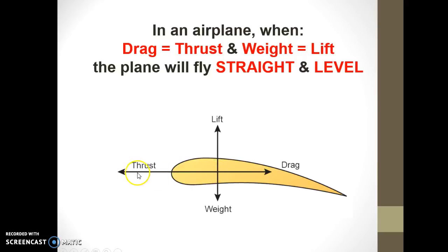We've got the thrust, which is our forward motion, which in your cars will be created by the CO2 cartridges. The drag, which we talked about, is either from that frontal pressure or the rear suction. Then we've got lift, any of the air that's moving to push the car off the ground, and just the weight of the car and how much wood you left in the car.